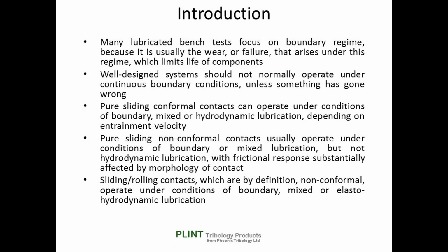It is perhaps not surprising that many lubricated bench tests tend to focus on the boundary regime, because it is usually the wear or failure that arises under this regime which limits the life of components. However, a well-designed system should not normally operate under continuous boundary conditions unless something has gone wrong, for example with the choice of lubricant.